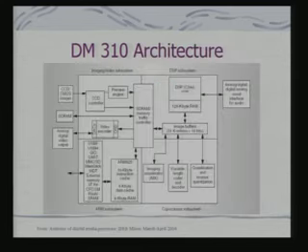So, the architecture looks something like this. You have got your DSP core, you have got your ARM core, and the DSP core makes use of these coprocessors, and this is your image buffer. So, this image buffer, which is onboard memory, is also being used by the DSP as well as these coprocessors, which are the imaging accelerator, variable length coder, quantization and inverse quantization blocks, and they manage it, and this is the basic SDRAM for other purposes, and this is a separate coder which is primarily looking at the video application.